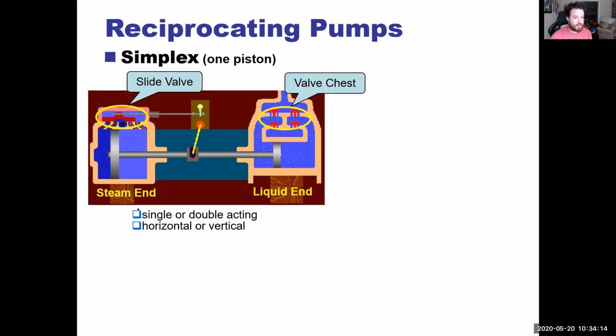So we do have an import feed pump. It's the simplex, one piston that goes up and down, and it's used in port because usually we're only going to have one burner on both boilers, and we're just going to be steaming just enough to keep, one, the boilers hot. Two, we want to make electricity, so we still want to run our turbines, our TGs. And this is still going to allow us to move feed water into our boiler at a constant volume.